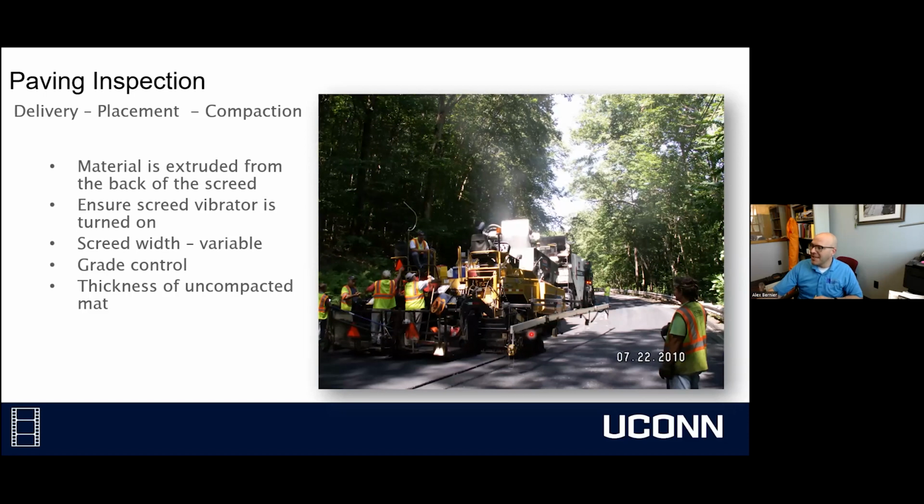And what's happening here is, if you've watched a construction crew long enough or seen pictures or videos, you may have seen in the olden days, and you'll still see it to this day when they're not using technology, there'll be people on the back of the screed making adjustments to these cranks. What they're doing is they're manually raising and lowering the screed from its toe point, which is all the way at the center of the paver.